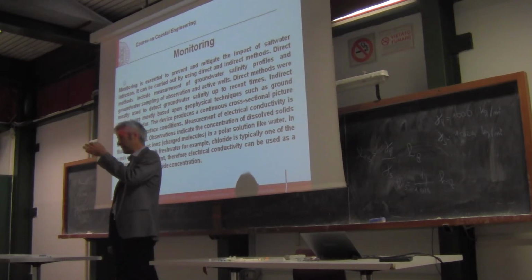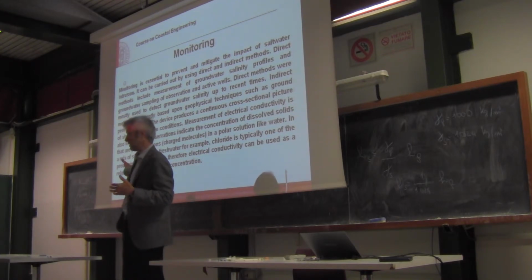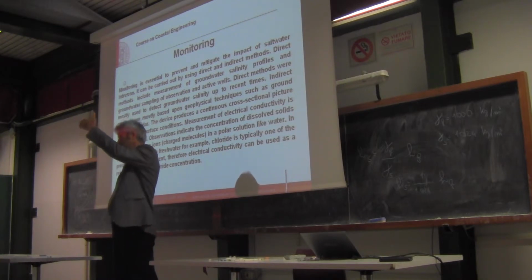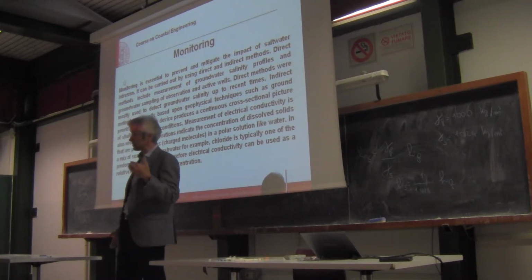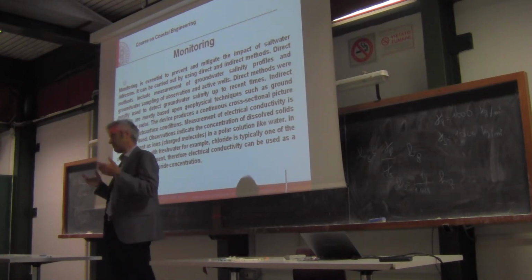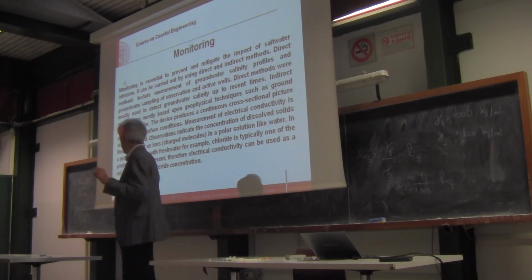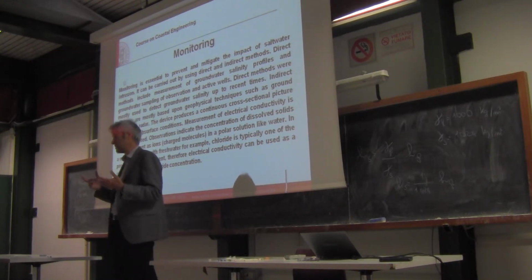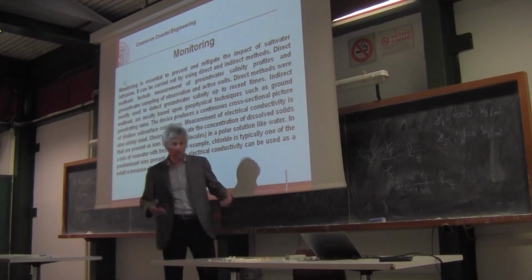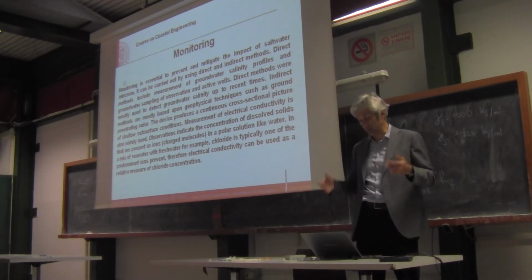And we need to monitor the aquifer at different depths, because you have seen that the shape of the saltwater intrusion is a wedge, and therefore we need to monitor salinity at different levels in the aquifer. But these pipes are relatively small, and they are not expensive to put in place. The only expense which is significant is related to actual monitoring, because we need to monitor groundwater with a frequency in time that is usually quite high.